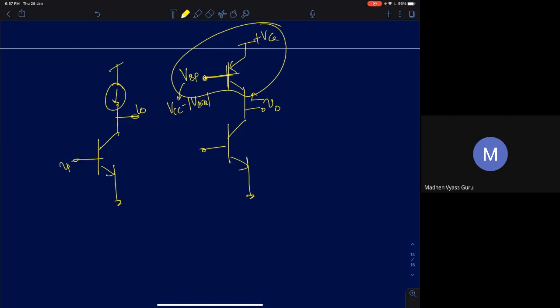We just discussed, no? For a PMOS, the current source is sourcing current, with R naught, right? R naught P. Let me call it R naught P. That's it. Take your NPN transistor, replace this with, for small signal, this node is at AC ground, and this is your output voltage. This will be R naught P.